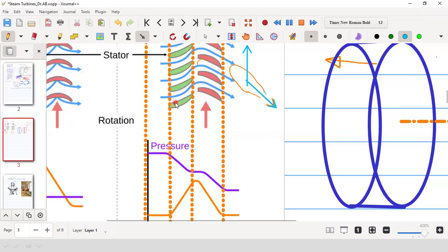Here, in the case of the nozzle, the fluid is getting the velocity and the nozzle cannot move. So all the expansion is now causing the movement of the fluid itself. But in the case of the blade, it can move. Therefore, the total kinetic energy gain due to the expansion is now shared by the movement of the fluid as well as that of the blade. Therefore, the kinetic energy of the fluid falls, and that is now converted to the kinetic energy of the blade, meaning that it is transferred.